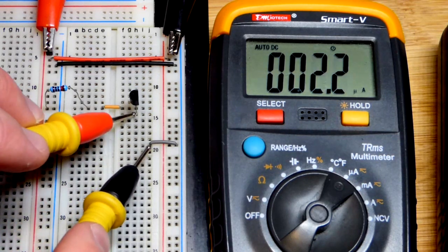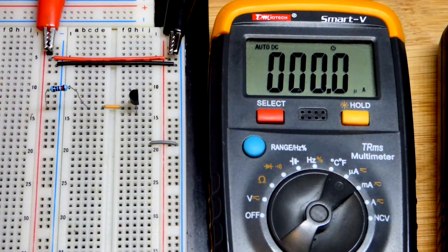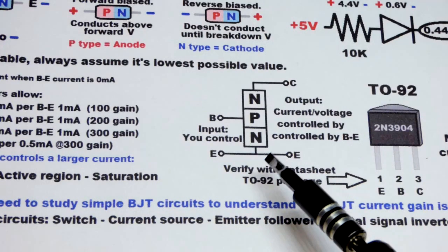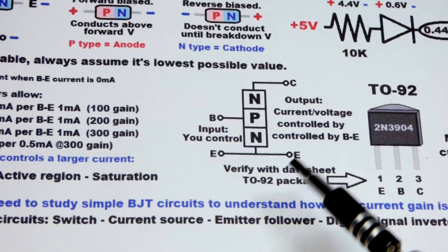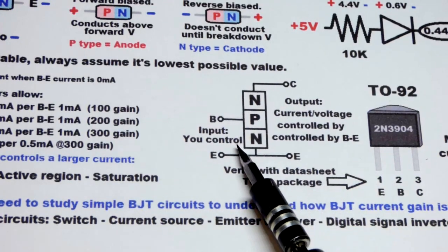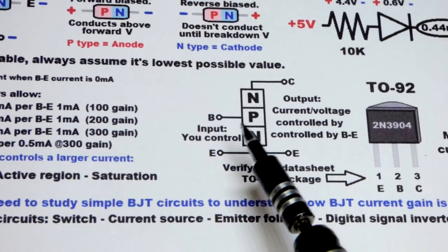So it's just a diode circuit, pretty straightforward. We covered that. So now we're going to move on. And so now we're back to the diagram. I did turn the multimeter off. It has a dial that goes to off, and if you don't have an off dial, just an off button, get it off of measuring current. That's the most dangerous thing you can measure by accident, too much current.